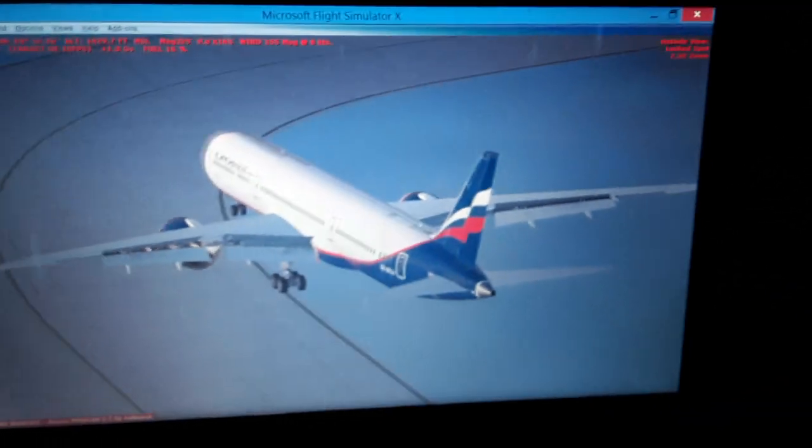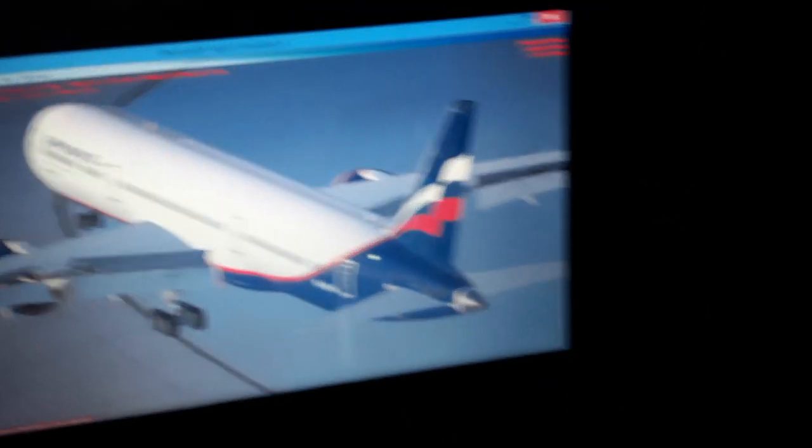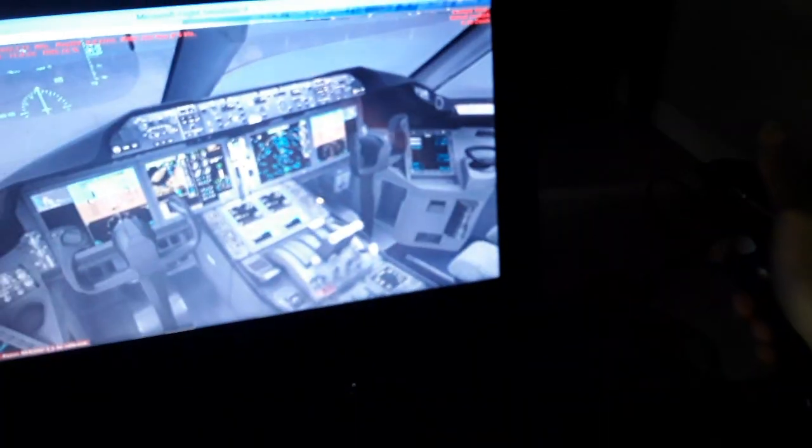So we can see here, we can climb, we can descend using the elevator, and we can also trim, use the horizontal trim stabilizer. So this is a fly-by-wire aircraft, as I'm telling you. Deflection in the ground is direct, like in the Airbus. So you have normal, alternate, and direct modes. If you have a failure, you have direct also.